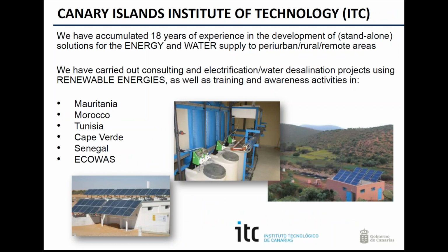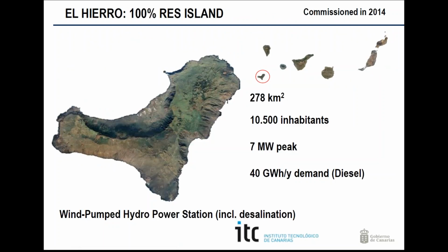The specific energy consumption has been of special interest, and this is the most variable factor in desalination plants' operation cost. It has a direct impact on the cost reduction of the desalted water. However, it will always require considerable amounts of energy. If conventional energy sources are used, they contribute to climate change, which in turn affects the water cycle and intensifies the original problem that desalination was intended to solve. For this reason, renewable energy sources must be used to meet at least part of its power requirements in the case of high-scale capacities, or totally in the case of low and medium scale.